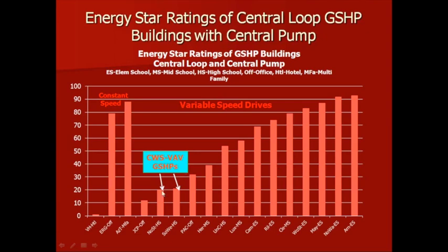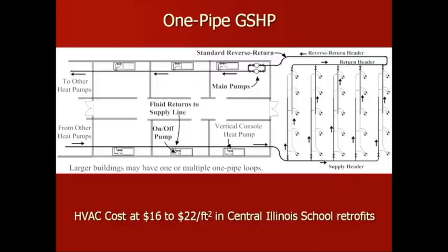We looked at 2 chilled water VAV ground source heat pump systems, and you can see there were 20s, okay? And people were surprised at that, and I just say, well, go back and look at the calculation similar to the one we did on the previous slide where we got the system COP. So these fans in these systems are using lots of energy. So it was not surprising to me that they didn't do too well.